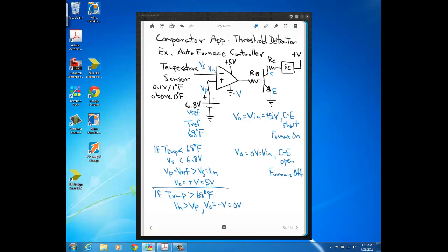So in a practical circuit, we use a component that under the right conditions acts like a voltage source, and that's a Zener diode. So this 6.8 volt reference, chances are in a real circuit like this, it's going to be a Zener diode operated in the reverse bias condition, acting like a 6.8 volt source. So you'd use a Zener diode with a VZ of 6.8 volts.